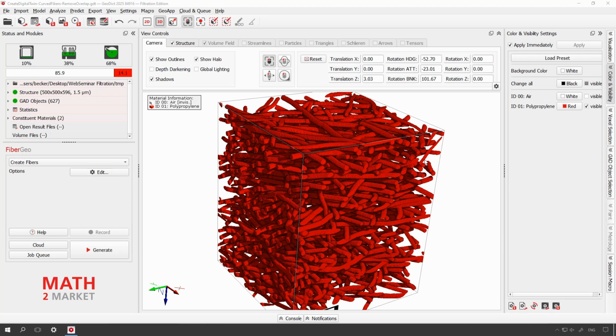If you look at the real material, you should always take more than one micro-CT image, maybe 2 or 3, and maybe one with a larger field of view, to get an impression if there are variations in the material, and that a cutout you simulate is representative of the complete material. If the filter has some holes somewhere where you don't look, this will of course influence the efficiency a lot.